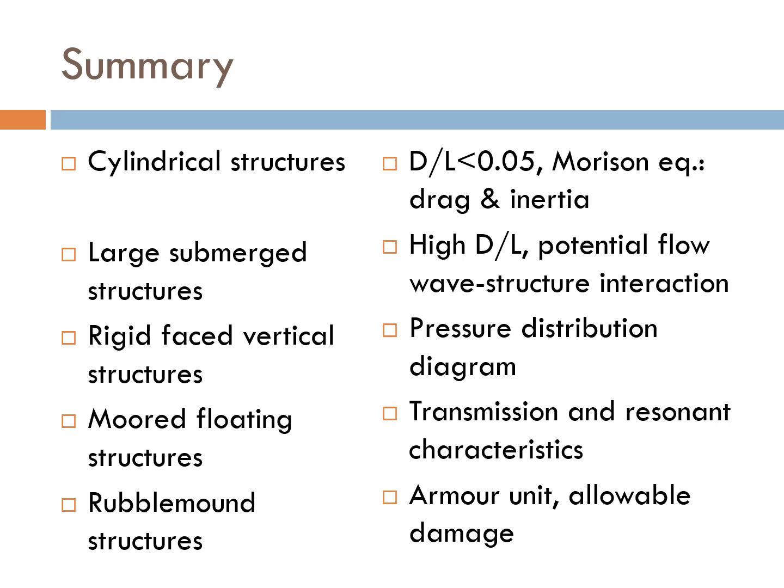For large submerged structures where the D/L values are typically high, the use of potential flow model is more common in order to investigate the wave structure interaction.